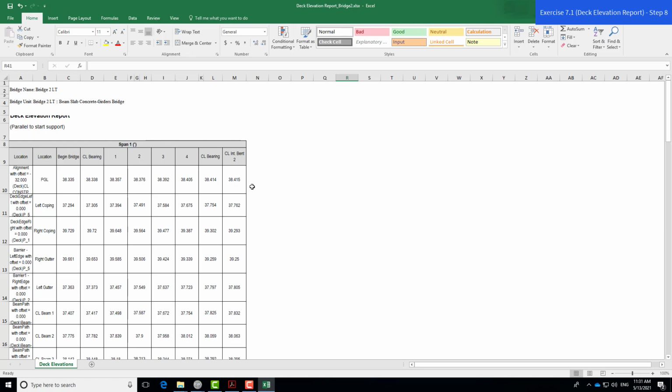The dates, like I mentioned, in terms of column widths or row heights, however you need to manipulate it. Also, these rows are not in the correct order, so we can move these around in order to get it the way that we need it to be formatted for the finished grade table. And then after it is formatted, you can then import it using your import method of choice, either the FDOT Link Data Manager tool, the OBM Place Table tool, or a third-party add-on if you'd like. So now we've got a good starting point for our finished grade elevation table.